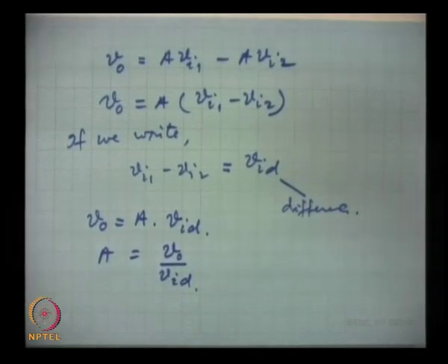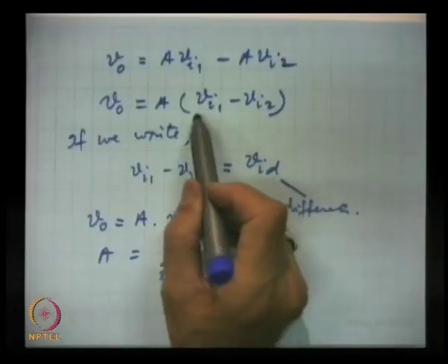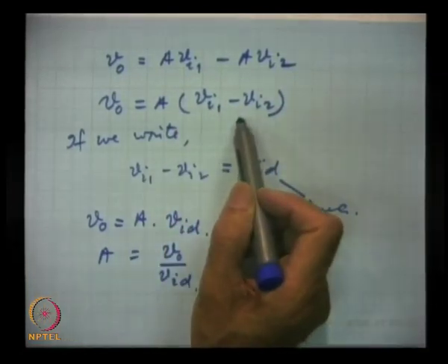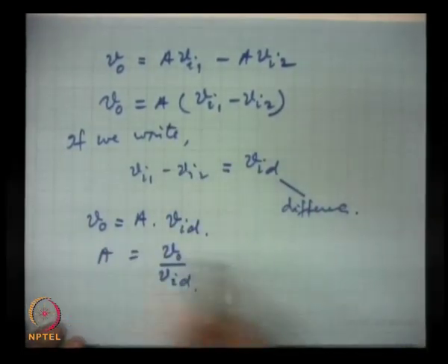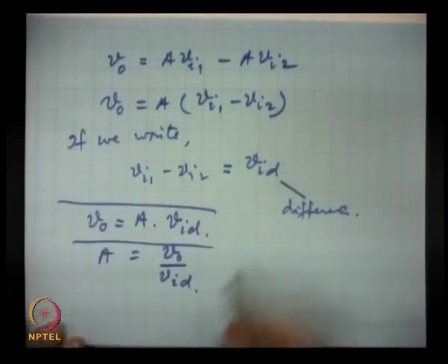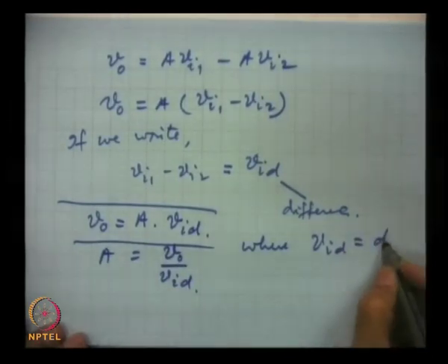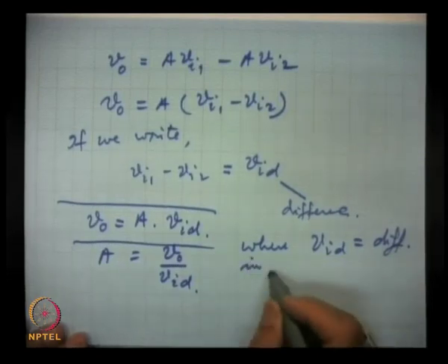That means this is what earlier we said as a statement. Now mathematically by the AC analysis this is coming true, that the differential amplifier amplifies the difference of the two signals, and so we can write the output like this, where VID is the difference in two inputs.